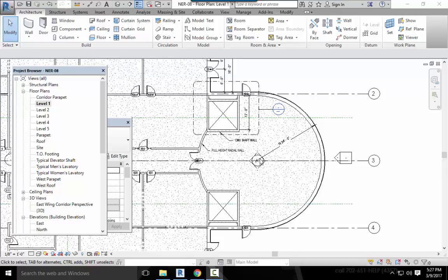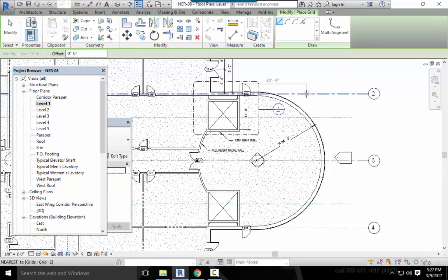So on the Architecture tab, click the Grid button if it's not already selected. So go Architecture, Grid. Item 2, pick the center of the radial wall. Well, they're already assuming that the draw line is there. So the best way to pick the center of this wall is type in SC. You'll see when I roll over that, the center comes up.